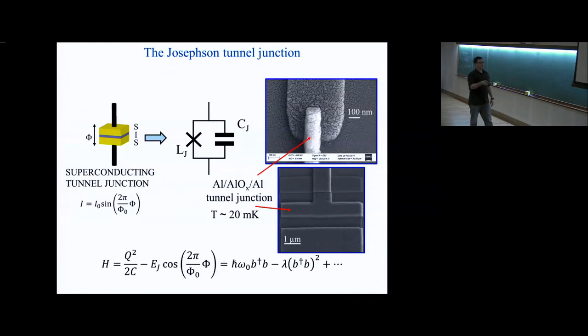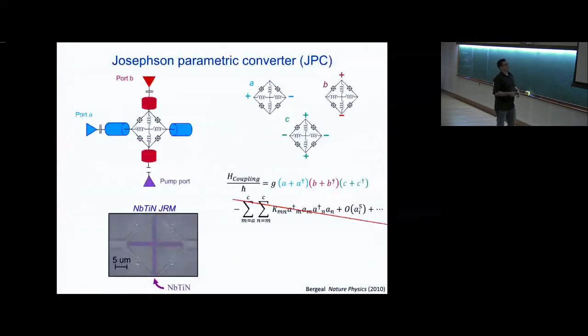So today we're only focusing on the big junctions, making these weakly anharmonic devices that are going to be our parametric amplifiers and devices. What we make in the laboratory looks something like this. It's 2 lambda over 2 resonators. In the middle, ignore these central elements for a moment. What you see here, there are 4 junctions in this Wheatstone bridge configuration.